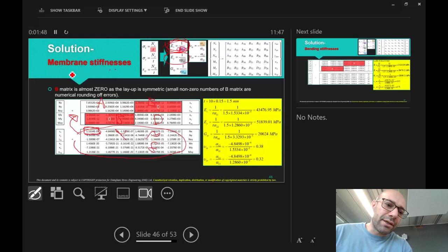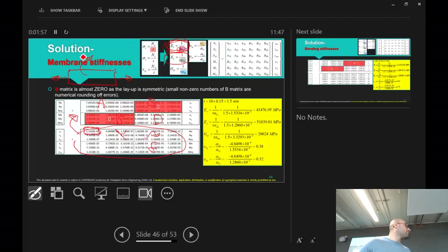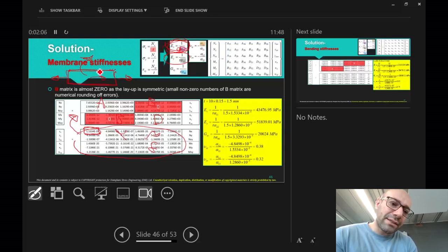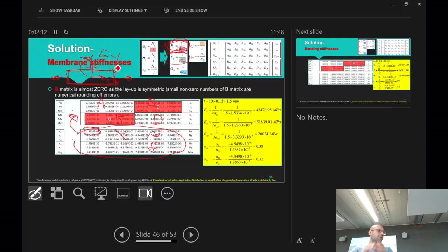So this laminate, in a very simplistic way, is under tensile loading. And this laminate could have 20 plies, 30 plies, 40 plies, you name it. In the case of an aircraft, it could be 100 plies or 300 plies. I want to know, for this laminate which has so many plies, what's its EX and what is its EY, so I don't have to deal with all those plies and can just see it as one plate.